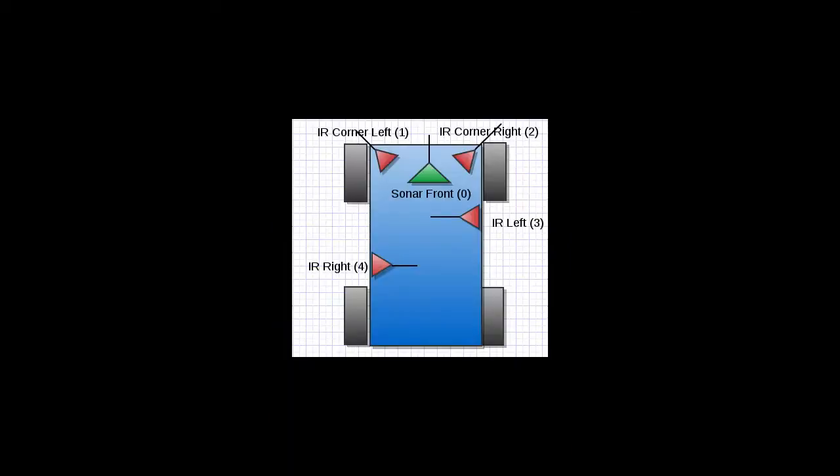As you can see from the pictures, our rover utilizes 5 IR sensors facing different locations: left, front, front right, and right. In our testing and design process, this is all we thought we would need and was all we ended up needing. Rear-facing sensors, as some teams used, weren't necessary because the course would not change behind us and we didn't have to worry about other things navigating the course at the same time.